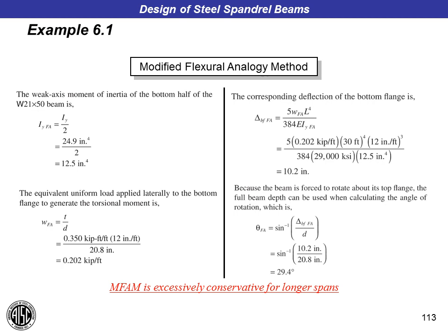So one way to do that is to provide kickers or braces, and we'll get to that in just a second. For comparison, if we were to use the modified flexural analogy method instead of the Design Guide 9 method, we'd find we get an even larger rotation.